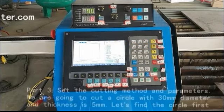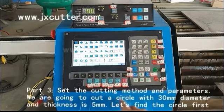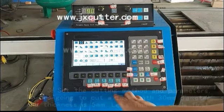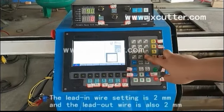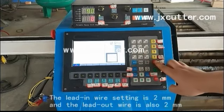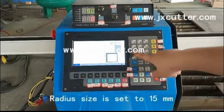Part 3. Set the cutting method and parameters. We are going to cut a circle with 30 mm diameter and thickness of 5 mm. Let's find the circle first. The lead in wire setting is 2 mm and the lead out wire is also 2 mm. Radius size is set to 15 mm.